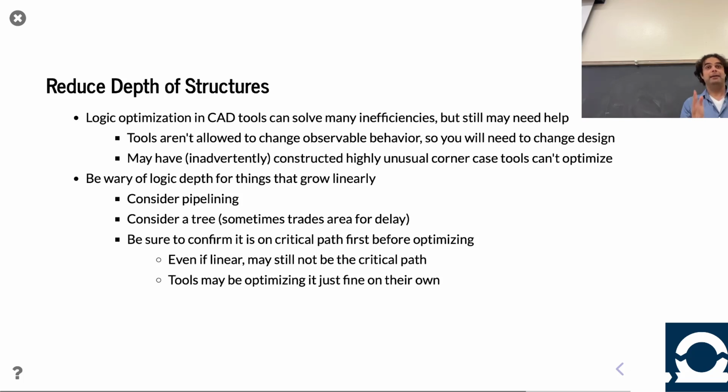That looks really bad. But every synthesis tool I've seen in my career so far has fully understood what that meant and did the right thing. It turned those 500 2-to-1 muxes into the appropriate deeper muxes in some sort of tree. So the tool figured it out, and maybe you're handling it just fine. So really make sure, before you dive into optimizing too heavily, that it's needed.